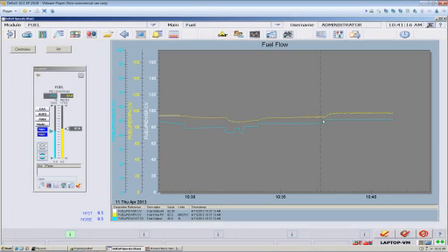So using these numbers that I quickly estimated, some of the lack of quickness here was just my talking. To actually get the data, I made one bump test. I click there, click there, click there, click there. I've got all the information I need in probably less than a minute for a flow loop.